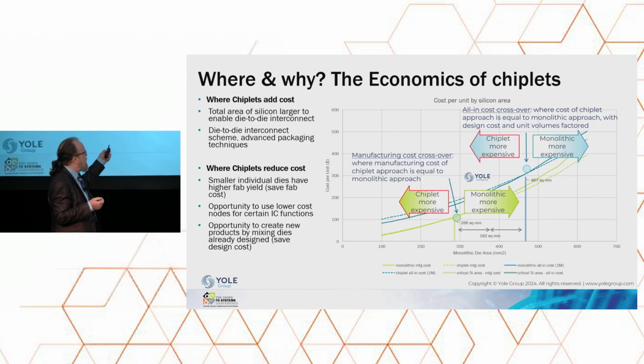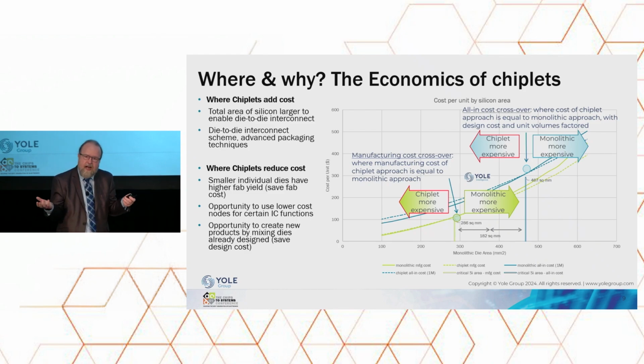And that is because there's a crossover. You're actually adding expense with the chiplet design in the fact that you have to design some sort of interposer, some sort of substrate, or some way of connecting those chips. And that has an overhead. And there may even be a little bit of a layout overhead as your solution may need to meet a common interface strategy that is industry standard. Whereas if you have it as a single monolithic die, you can basically design whatever routing paths you need to be optimal. So there is a trade-off there.